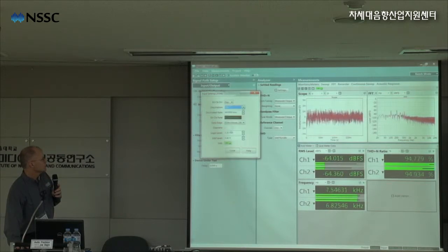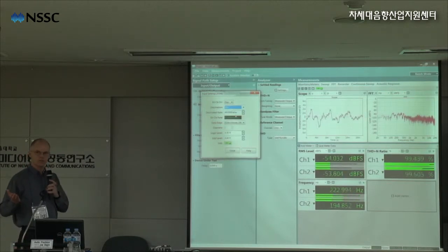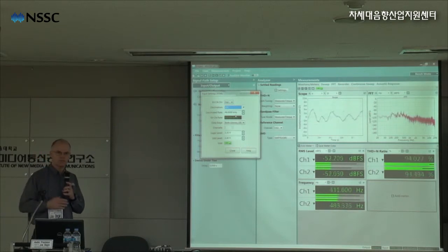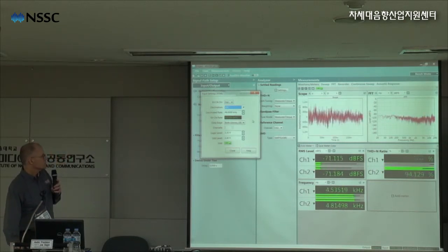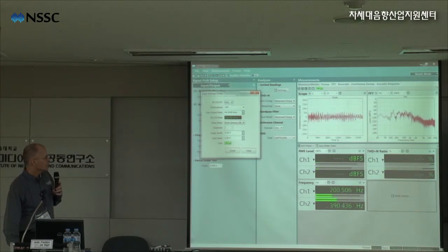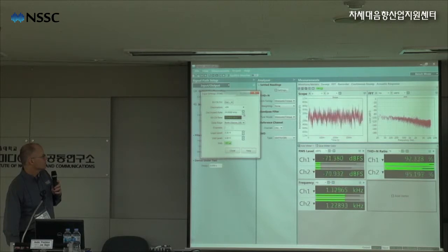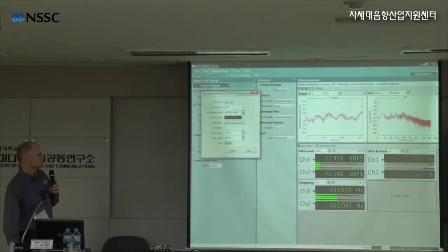And then there was a question about the relationship, I think, between the decimation rate and the sample rate. Let's try a different sample rate here. So if I go to 44.1 kilohertz with the same decimation ratio, now my bit clock rate is 2.822 megahertz. And I can go down to 32K, so now the bit clock is 2.048 and so on. So really the bit clock is changing in relation to the decimation ratio and the decimated rate.